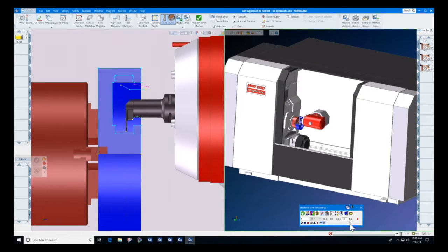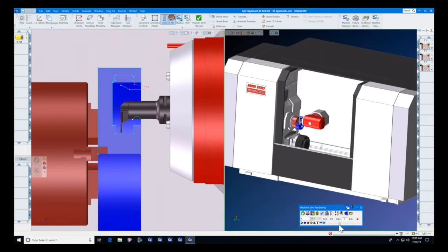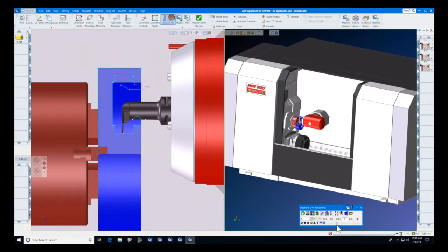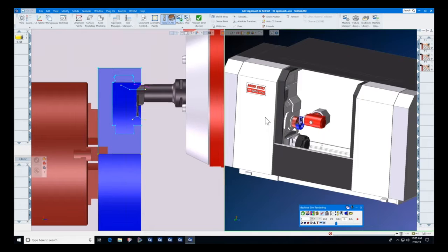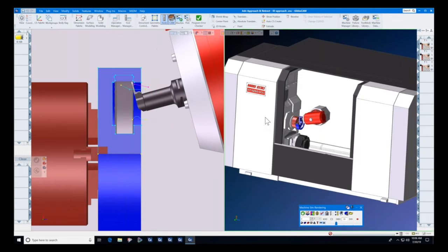And as soon as this tool path is done, we're going to slow down, and we're going to look at the entry and exit for the top of the groove using the same tool, but a feature in GibbsCAM that allows us to flip the tool over to another orientation on certain machines like the Mori Seikis, the Mazak Multi-Series, and the Okuma Integrex. Not only did we do that, but we can turn the head to a different angle and still rough with it at that angle.